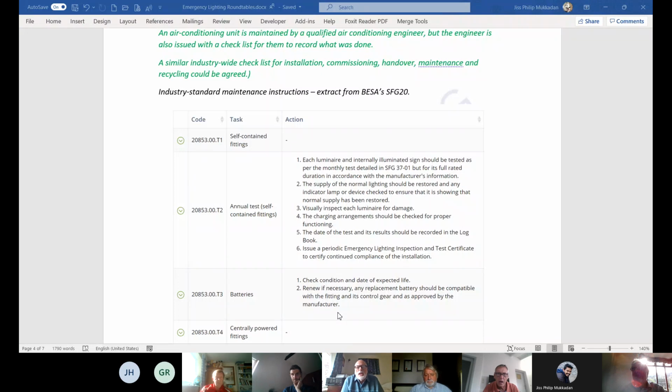So if it's been incorrectly installed, then that would have been identified, that they're not performing their function. Where we get a problem is where you get user interference, like drawing a curtain over an exit sign or a call point. That's the sort of idiot thing that is difficult to guard against, but at least it should be reported on, yes.